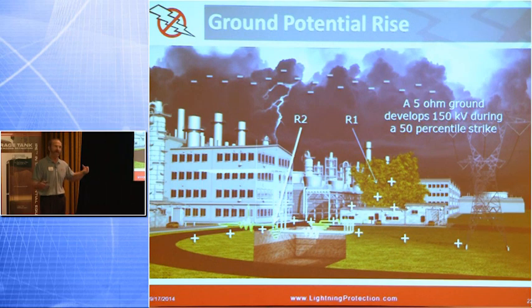Current's going to flow back and forth. If I got resistance and I got voltage, I'm going to have current flow. Natural principle of electrical discharge. And now these currents that flow trying to equalize themselves create all sorts of havoc with our sensitive electronic systems. Simple solution, tie them together. Make sure all your grounds are bonded together, connected together, at least in the earth. So when you have a lightning strike, they all rise and fall at the same potential. And so we constantly see this in the United States where these grounds are tied together.